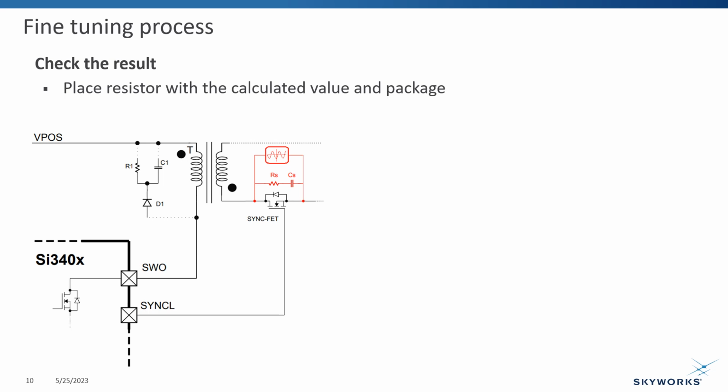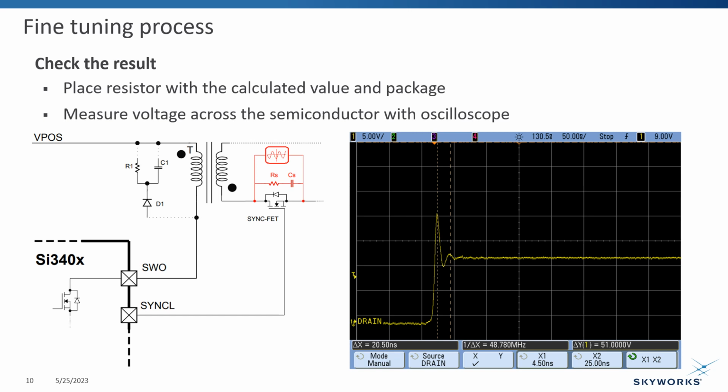With all the snubber part values and ratings in hand, what's left is to place the parts and check the results. A properly tuned snubber will leave some peaking but almost no ringing during the transients.